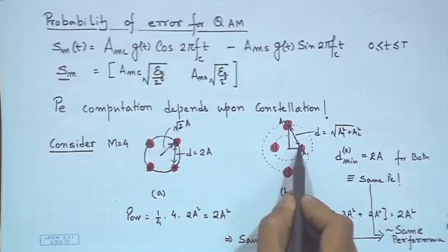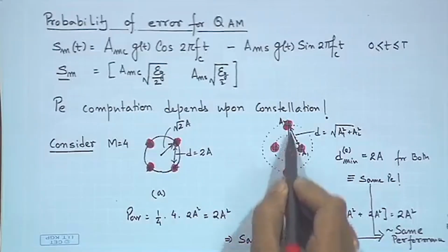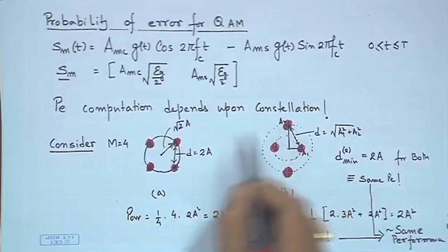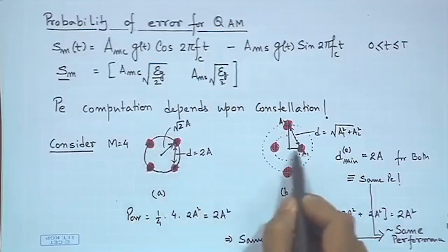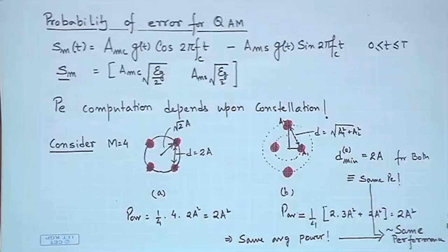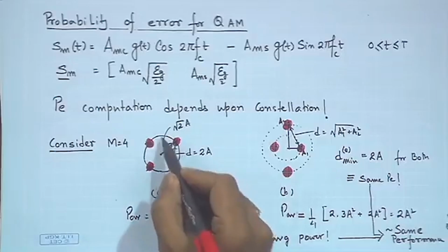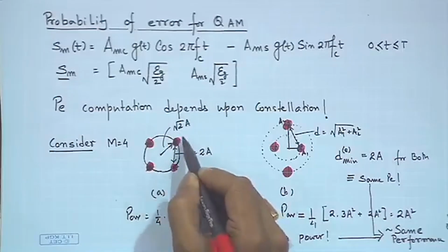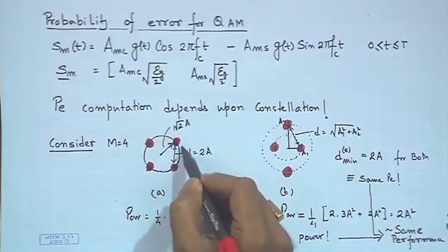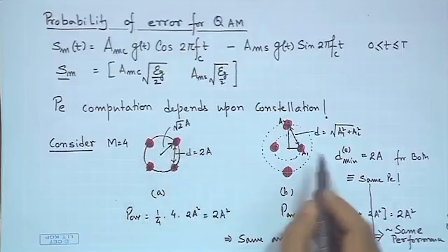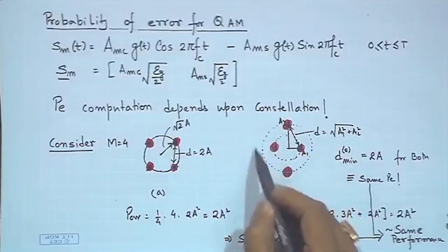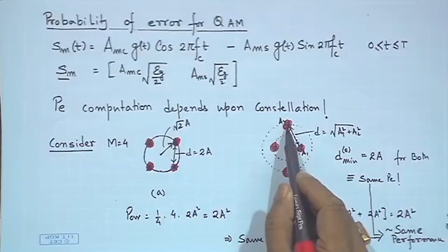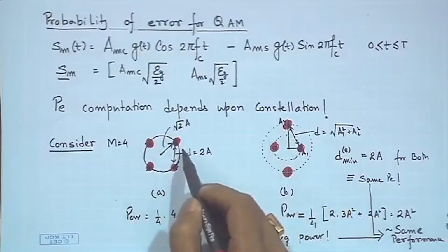So, this has lower power and this has higher power than the average, and the average would be the same as this, right. So, these are constellations which are closer, these are farther away. So, overall it has been maintained. That clearly means that the peak power to average power ratio for this is much smaller compared to the other. So, the peak power in this case will be higher than the peak power in this case.